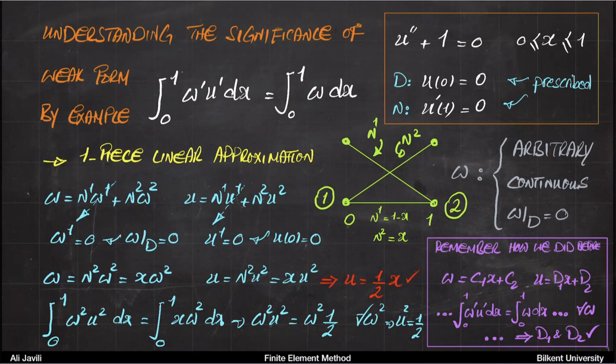And you can imagine if you want to solve a structural problem, this is a much more meaningful description of a problem from a computational perspective, because if you set up the problem the way that we did, so that the unknowns are the nodal displacements, then solving the system would give you those nodal displacements immediately. You don't have to have those intermediate steps.